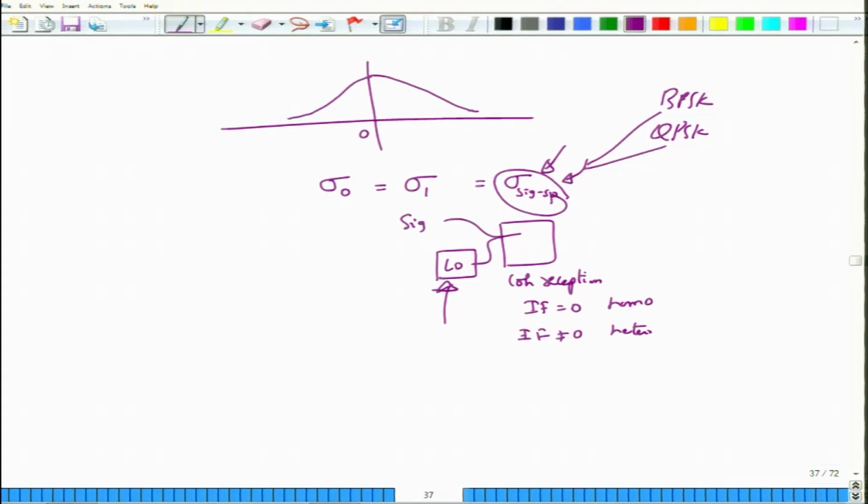Having said that, when you go back to on off keying, signal spontaneous noise will actually increase the sensitivity of the system, because when you do the expressions completely correctly, you will find that the BER would have been significantly reduced for the same launch power P1 and P0, because you have put an optical amplifier in before you gave that optical power to the photodetector.